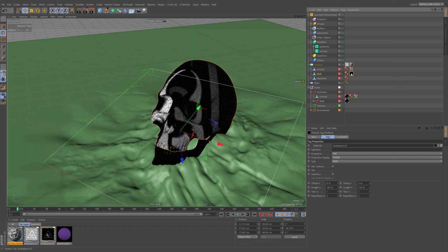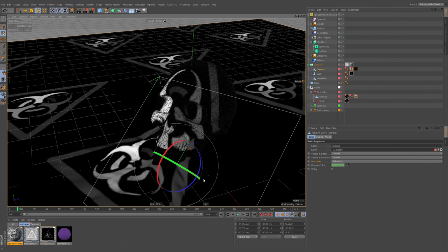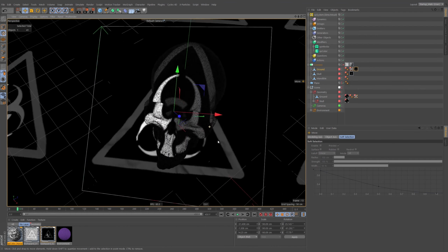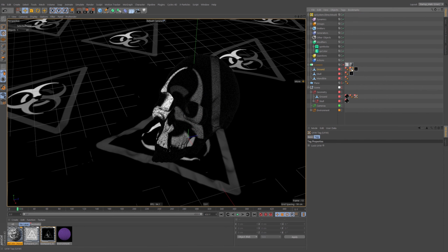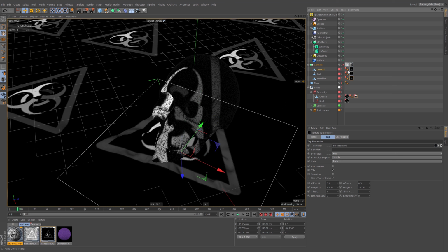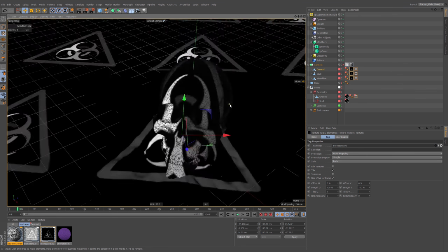Let's do right click. Once you've got it in position, let's duplicate it to the ground plane as well. And oh, the ground plane has its use color active. This is only a demonstration right here, so we're only lining this texture up and generating a UV from that. So I'm going to delete that one. And then the mandible. Then if I select all of them and right click, once I've got them into position and I hit generate UV coordinates, we've now got UVs that we can utilize to apply textures to our object. Very crude, but they'll work.